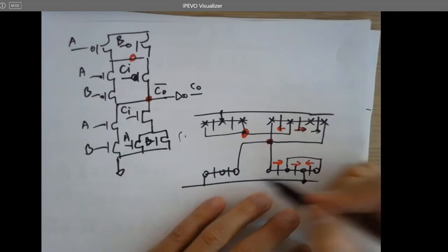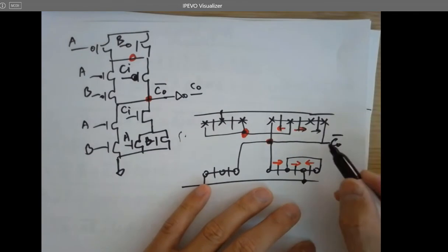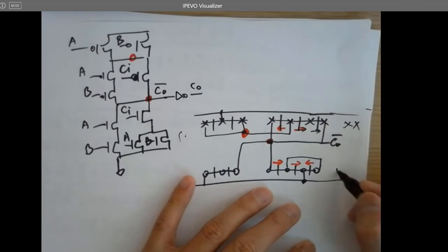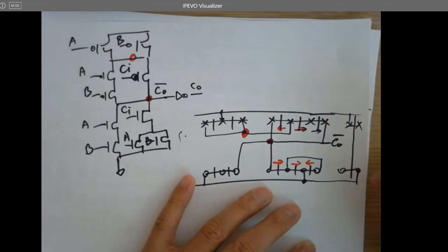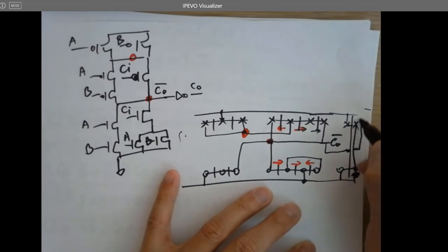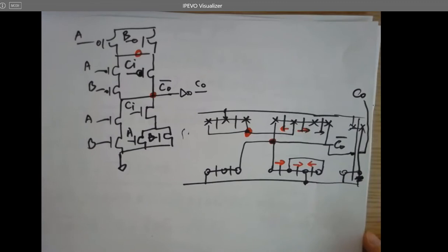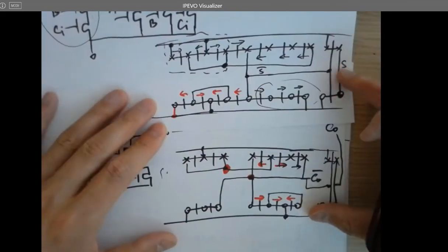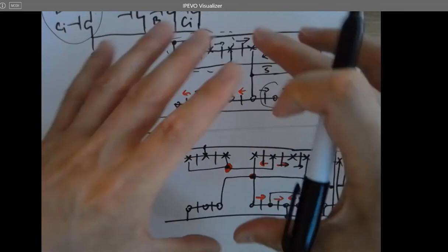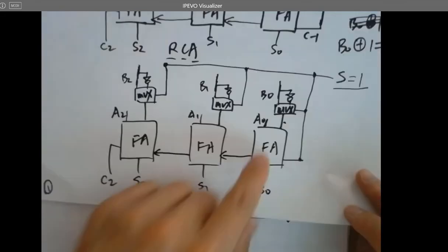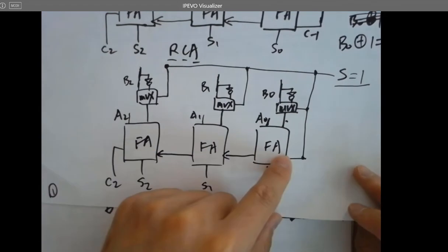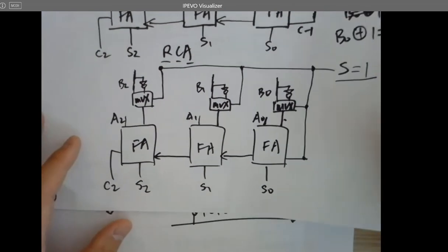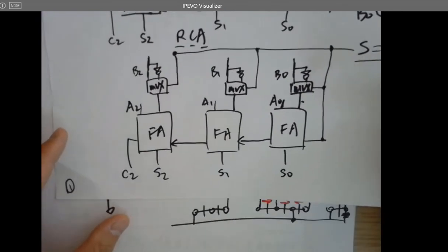So the output from this stick diagram is CO0, and you want to invert it. Just add an inverter after it. So here is CO. This combines these two layouts so you can get a compact version of the adder. Then you just put everything into a box symbol so you can use it for this circuit. You can form a 3-bit subtractor, or if you just add more, it's going to be an 8-bit adder, which are going to be used in the lab tomorrow, I guess.